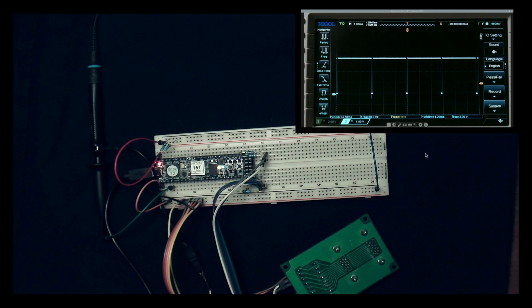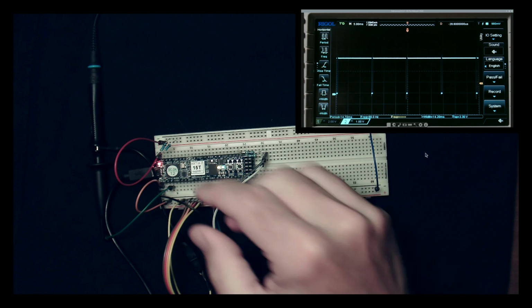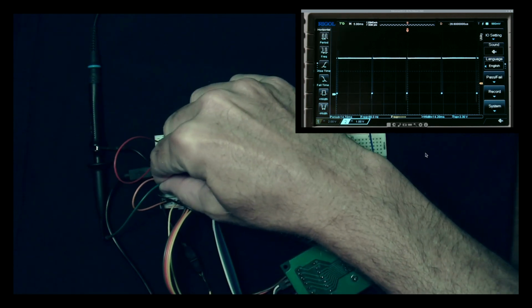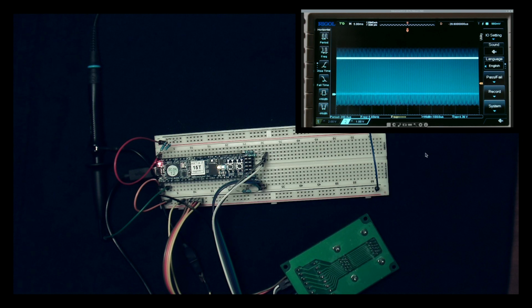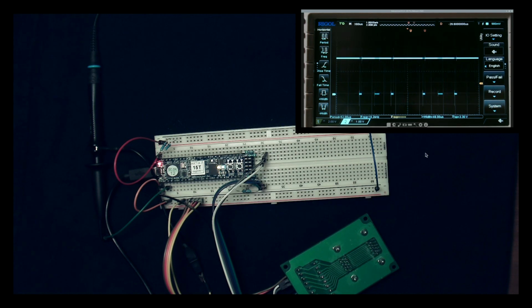And we are getting a frequency of 68 hertz, which is much closer to the 68.1 on the calculator. Let me change it over to the horizontal sync. And that's coming in at 18.7, and this says 18.75. So that looks definitely correct with a period of 53.4 versus 53.33. So yeah, I would say this is now working.